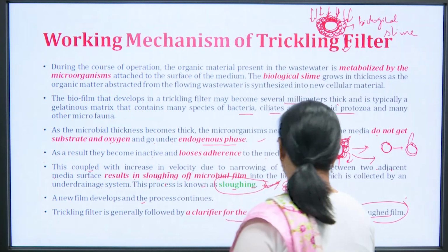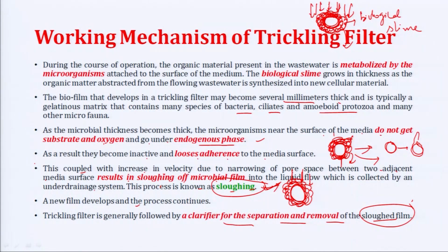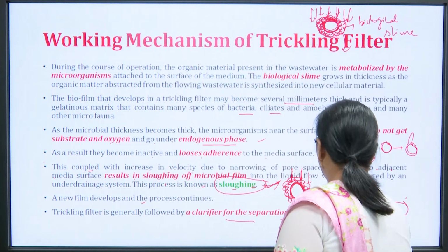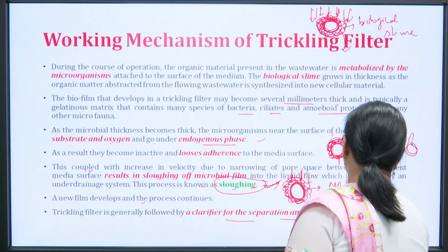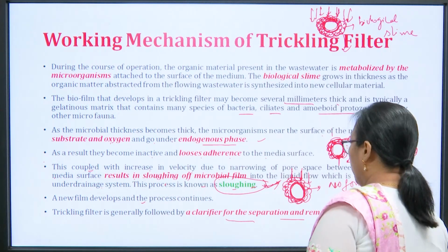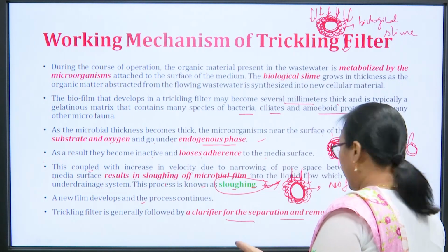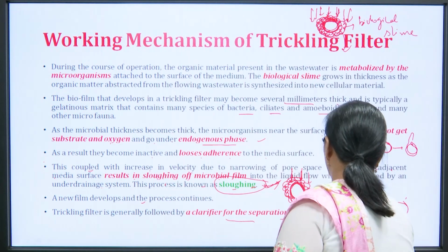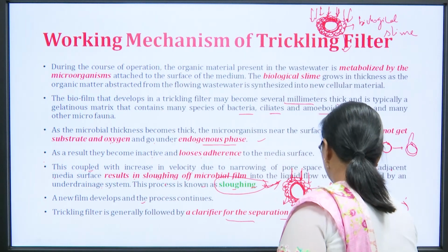So, this is going to keep on getting bigger, but the process of getting bigger means that the bacteria sticking to the filtering media, the inside, they are not going to get any food, no food for them, right. What will happen? If you do not get food, those bacteria will start dying off, right, and then thus adherence will be gone. So, they are going to fall off. So, this will fall off.